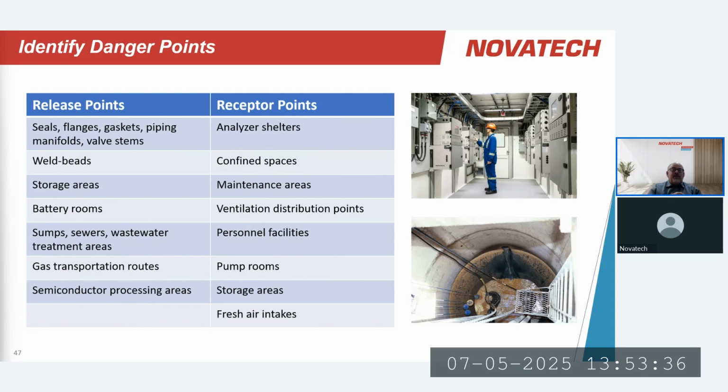Battery rooms are becoming a bigger and bigger thing. Batteries, depending on the nature of the types of batteries that are being used, can generate hydrogen oftentimes. So knowing that here we've got a thing that actually can make hydrogen, are we taking the necessary steps to monitor for the presence or the accumulation of hydrogen in this environment?